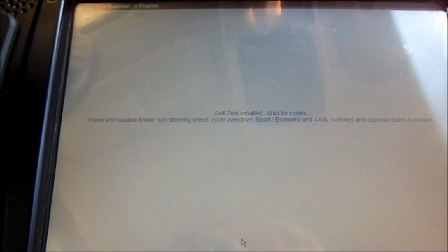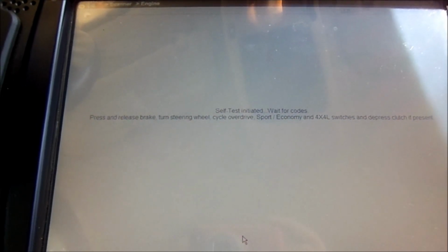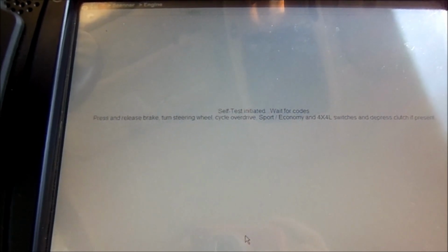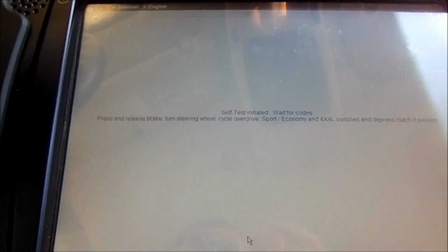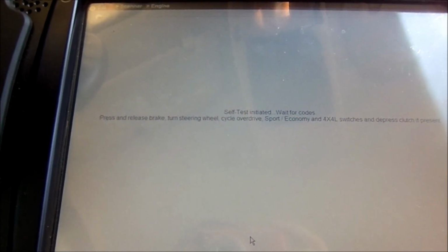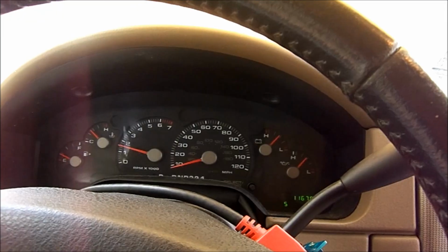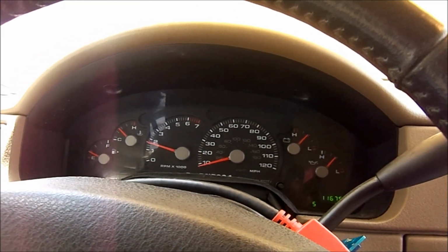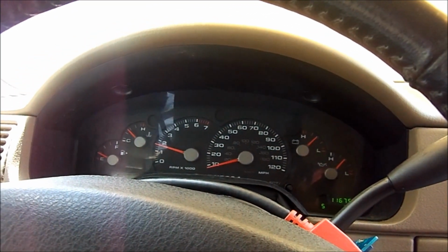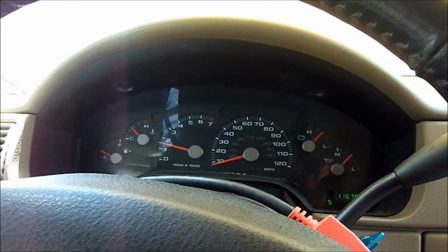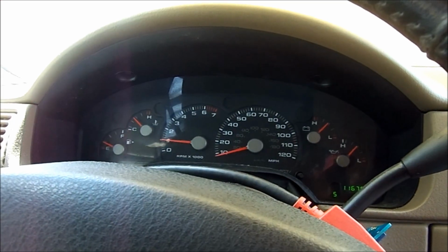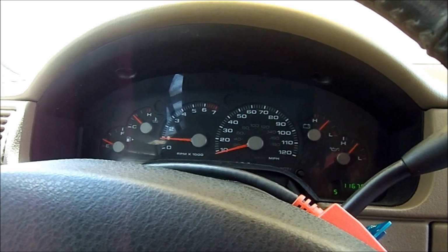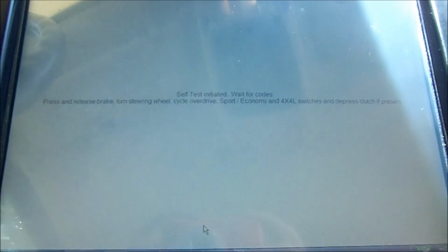And if you saw on the freeze frame records, 10 miles an hour, that's all it took for the P2106, for that throttle actuator going to forced limited power. So still running the test. We're at about 1700 RPM. Okay, engine idle, RPM is dropping, so it's probably almost finished doing all the tests.